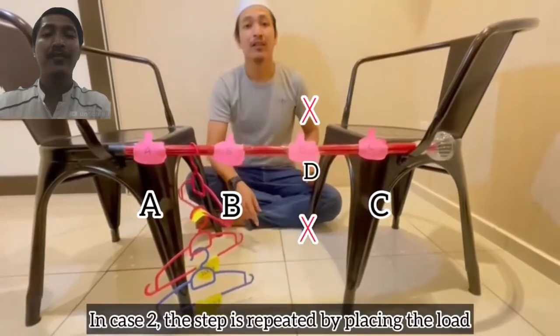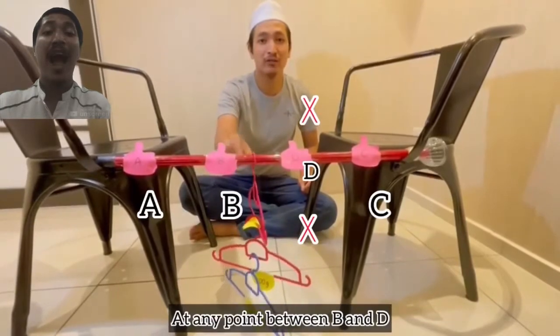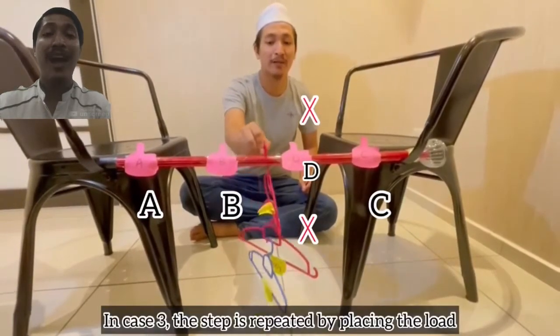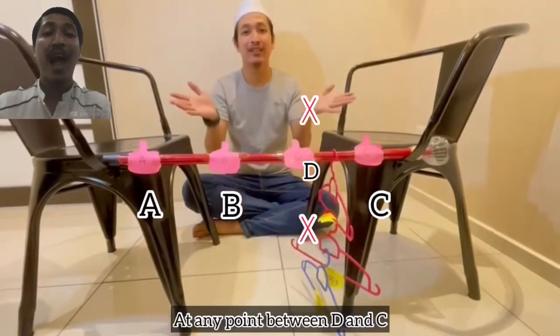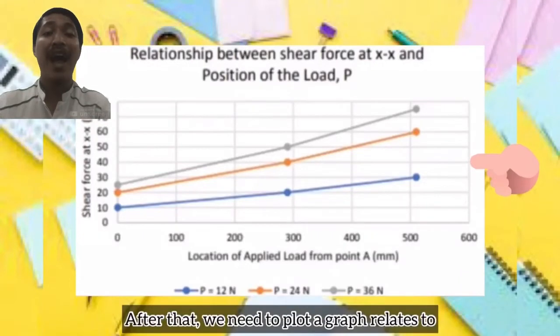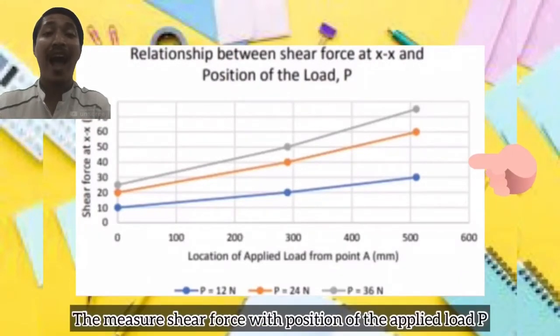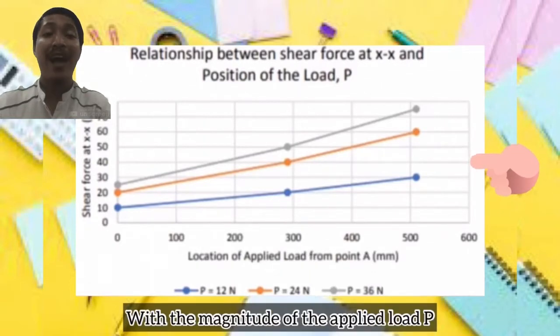In case 2, the step is repeated by placing the load at any point between B and D. In case 3, the step is repeated by placing the load at any point between D and C. After that, we need to plot a graph relating the measured shear force to the position of the applied load P, and a graph relating the measured shear force to the magnitude of the applied load P.